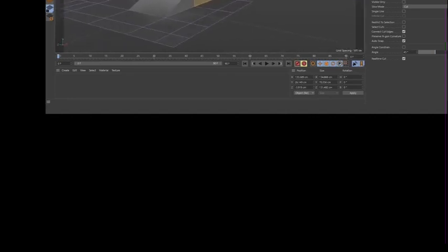To cut through the polygon, tick the Visible Only parameter checkbox off. The Loop Path Cut tool allows you to create one or more cyclic cuts.